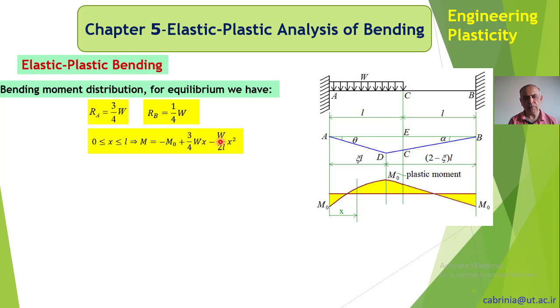So we have W over L times X giving the load up to point X, and then times X over 2 gives us the moment. I omitted this 2 in the previous slides, but I have corrected it here. Also I have corrected it in the PowerPoint as well.